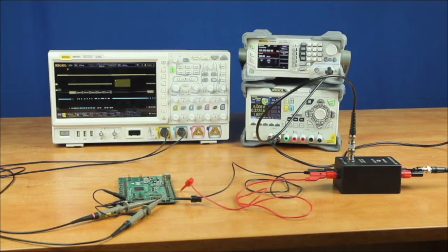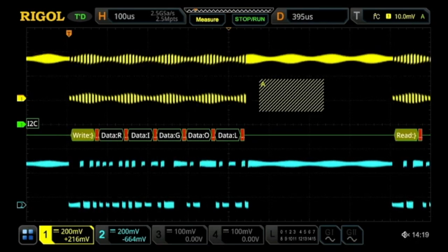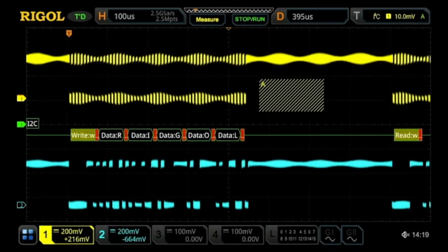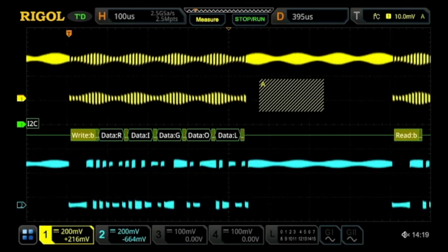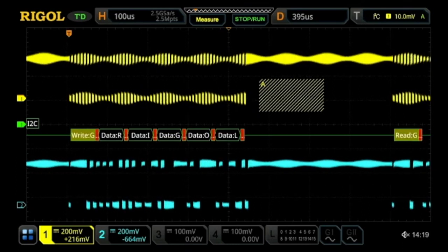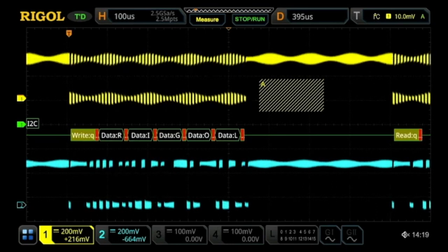Let's go ahead and look at the scope. Here, as we start to turn the power up, we start to see some effect on modulation on our signals there. Not as much as from the radiated high power emissions, but still seeing some changes that could affect operation. So this is a great validation check to see where you are in terms of conducted immunity testing.